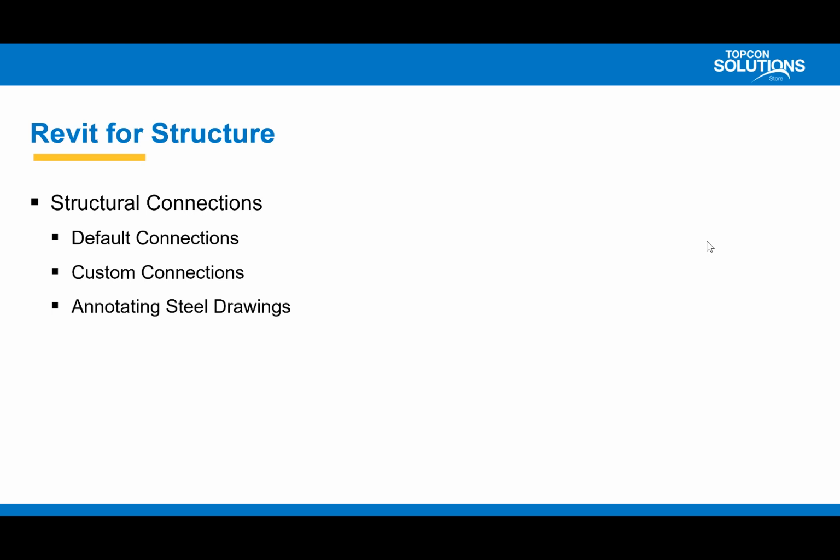Okay. So with structural connections, with I think it was the second update of 2018 into 2019, they gave us the structural connections, right? 2019 and into now 2020, we're starting to see that we can customize those connections like we haven't been able to before. I mean, yes, you can make plates and adjust your bolt assemblies or their layouts, but it's also just creating your own, specifying your welds, creating side plates or stiffeners, web stiffeners, flange stiffeners, specifying all of this while you're designing it out. And then being able to group all of those elements together into a connection, okay?